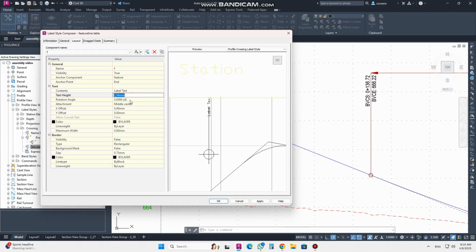Okay, the label text, the size of the text here, I will okay, with the middle center, it will attach to the middle center. So if you want to move it a little here to here, just write the x value -5, and you will see it will come down. For the y value, if you move up and down, put the value here, and if you want to move like this, just change the value here.